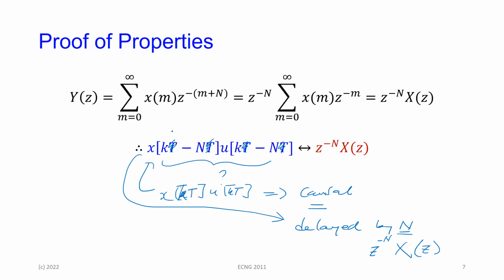Why? Because we said that a difference equation is just a set of delayed values. So if I tell you y(n) equals y(n-1) plus something, this is a delayed version of that. Like your counter, it is the previous value or the previous set of values. This is what we call the difference equation. So the Z transform of this is simply (z minus 1) Y(z). Okay?